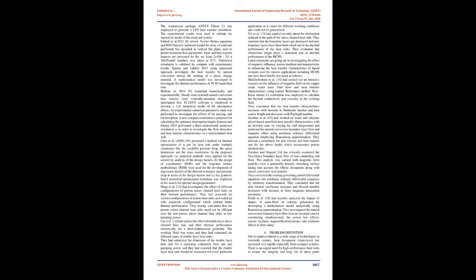Sable et al. 2010, 6. Investigated the natural convection of a vertical heated plate with multiple V-type fins having ambient air surrounding. The mica-clad nichrome element is inserted between two base plates. Mahmoud et al. 2011 conducted an experiment to investigate the effects of micro-fin height and spacing on heat transfer coefficient for a horizontally mounted heatsink under steady-state natural convection conditions. Fin height ranging from 0.25 to 1.0 mm and fin spacing from 0.5 to 1 mm was taken.